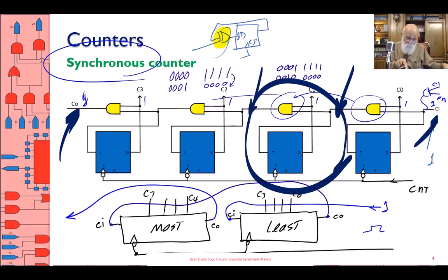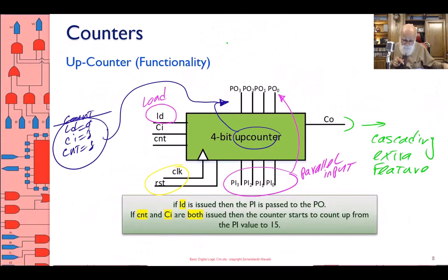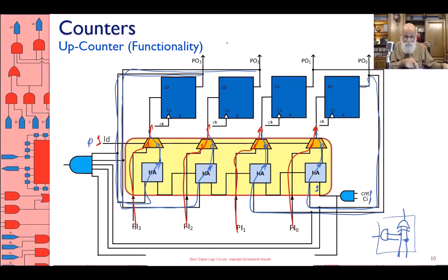Actually, this circuit is not very different from this circuit, considering the half adders only, not considering the parallel inputs, because that AND is this AND, that XOR is this XOR. See how the ANDs go from one half adder to the next, to the next?